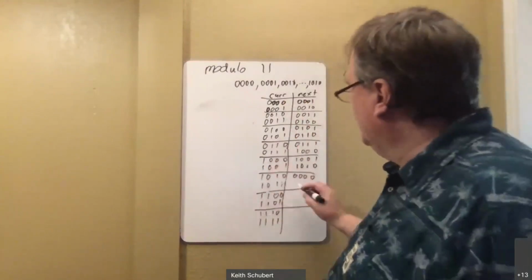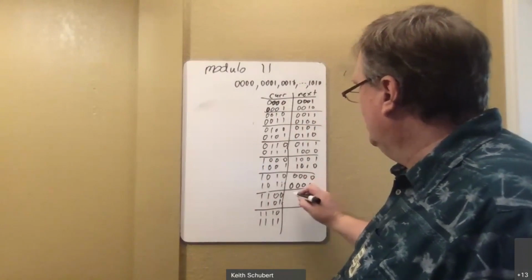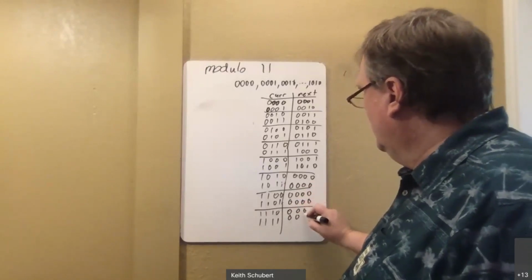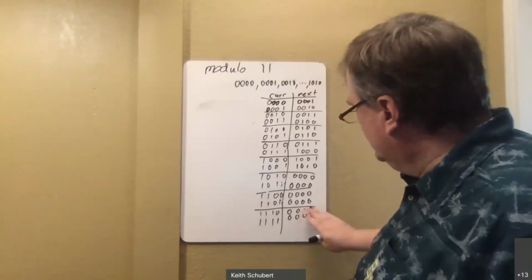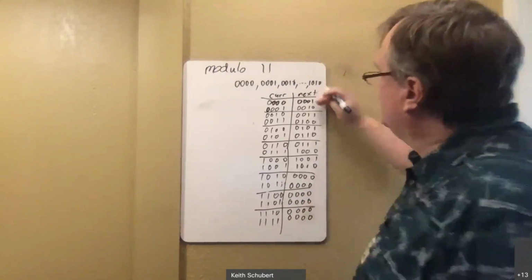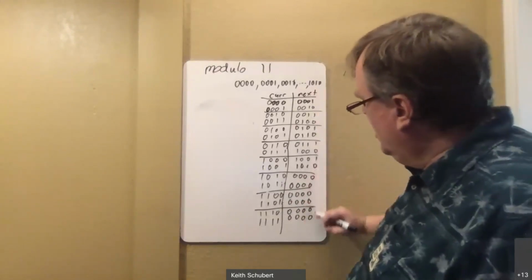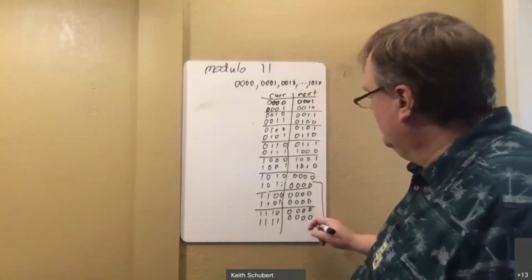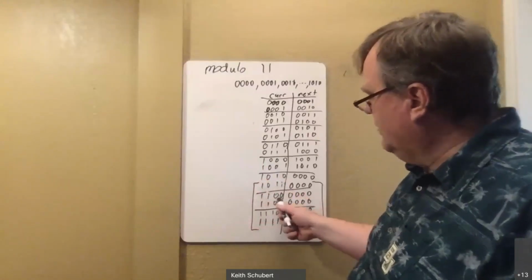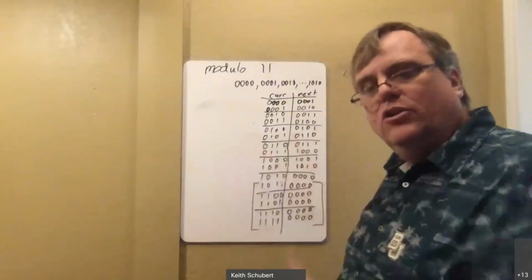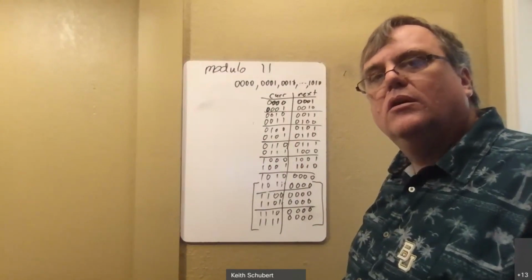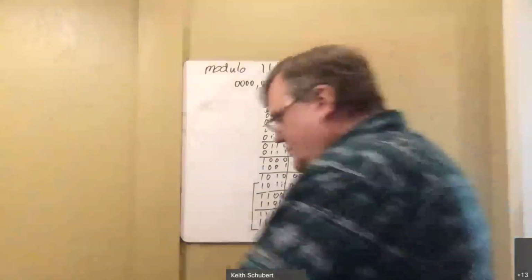But I've got more than enough stuff. I am going to currently just make these all zeros, just restart my counter. That's not 8, so those are zeros. So this is my modulo counter with the unused things down here. Because 10 going to 0 is legit part of the counter. But this part down here is unused, which is states 11, 12, 13, 14, and 15. Is that good? Yes.